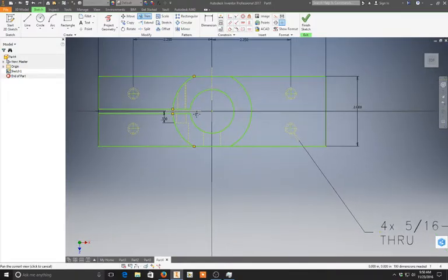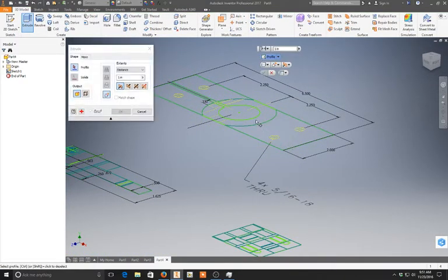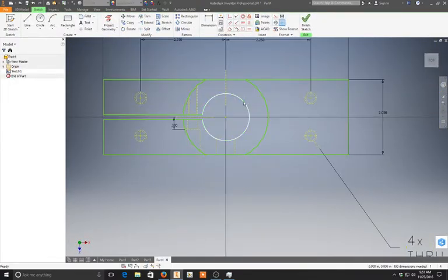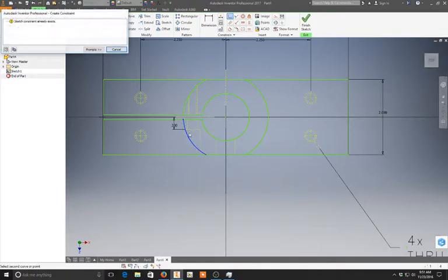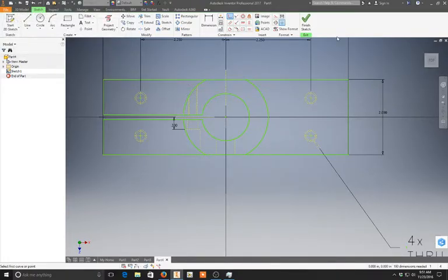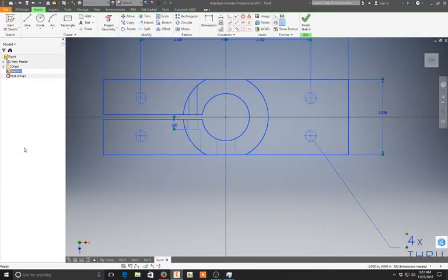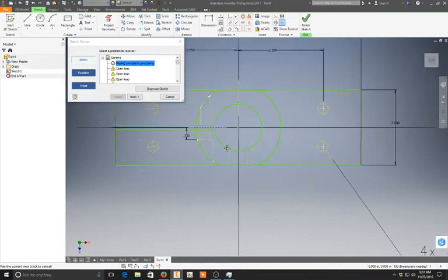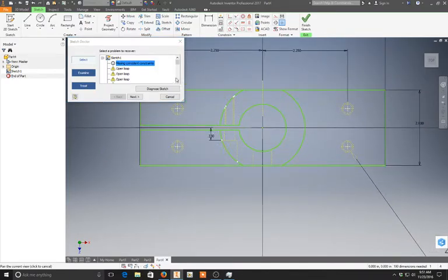And we'll just see if that fixes anything real quick. Okay, we're getting really close. Okay, so now we're just going to try, let's just try a few coincident constraints just in case they're not already there. And let's try the sketch doctor. Okay, none of these coincident constraints are important for us.